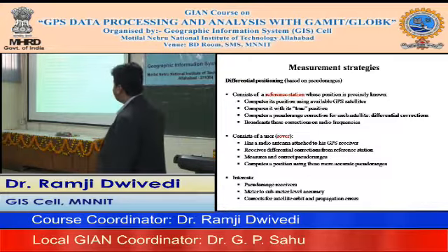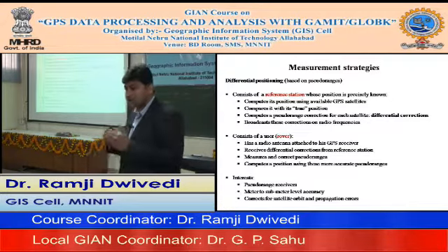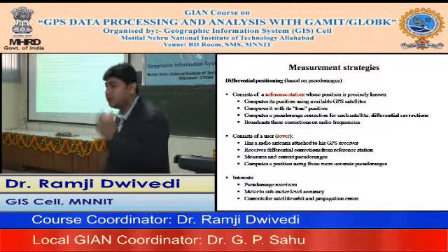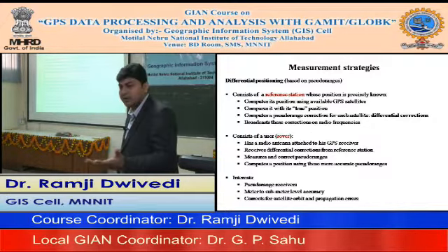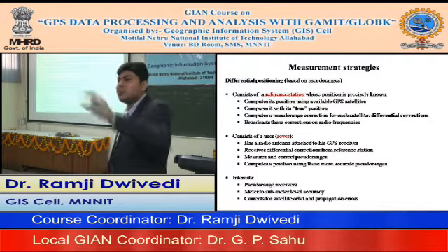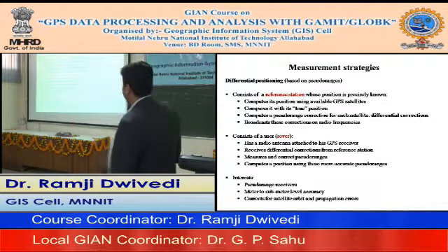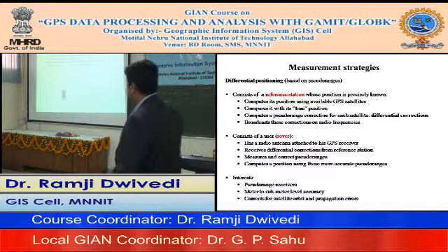Okay, so DGPS consists of a rover and base, and obviously if you have to transmit the correction from base to rover, you need a medium through which you could transmit it. So generally radio modem links are available, and certain formats are also available, of which the popular one is the RTCM format. You could read about it in the literature, and in that format you are getting the corrections from base to rover. So this is one simple example. It's again from the Seeber book.